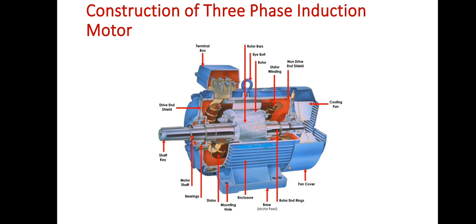Then if you go to the stator terminal, the stator has the stationary armature. The armature has three-phase nature: R phase, Y phase and B phase. All the three phases are displaced by 120-degree phase difference. The stator also has a core and slots. Normally semi enclosed slots are preferred for this type of machine because the flux passing area would be very high. Secondly, maintenance is easy if any windings are damaged.